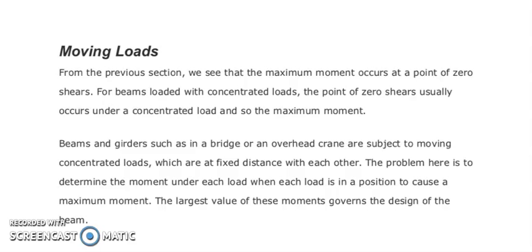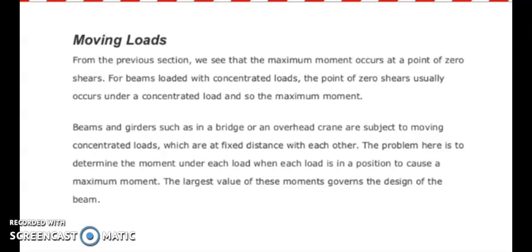Okay, our discussion is on moving loads. From our previous discussion in the previous section, we were able to identify that maximum moment occurs at a point of zero shear. So for beams loaded with concentrated loads, take note that the point of zero shear usually occurs under a concentrated load, and so the maximum moment.